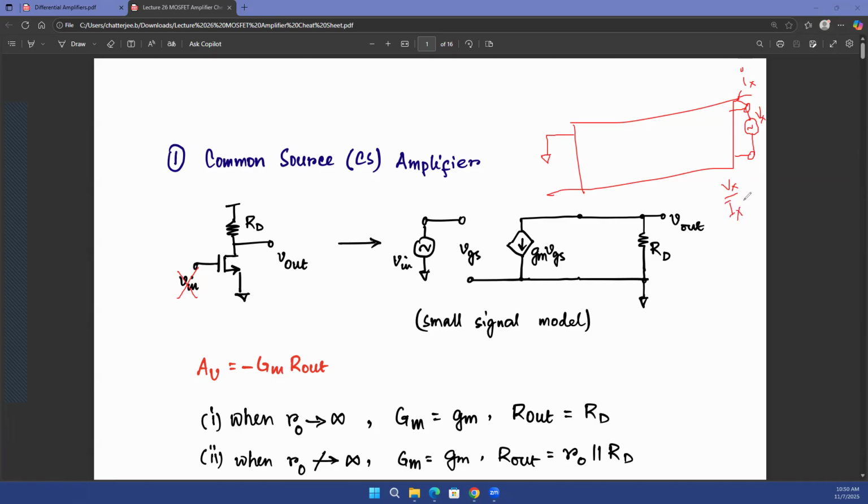Again, nothing new here, just something that you learned in 3111, how to find out Thevenin equivalent resistances. Vx over Ix is your R out for this black box in a no load condition. Remember that we had removed the load in the beginning. So whatever we find out as Vx over Ix is without any load because we have removed it.